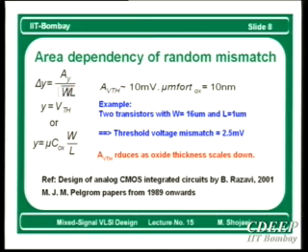First of all, it can be shown that any variation in any parameter in a CMOS transistor is proportional to the square root, sorry, this is the square root, okay? You just correct it. It is proportional to the square root of the area of the gate. And these parameters, this A_Y is essentially a process parameter, and delta Y is effectively the standard deviation.